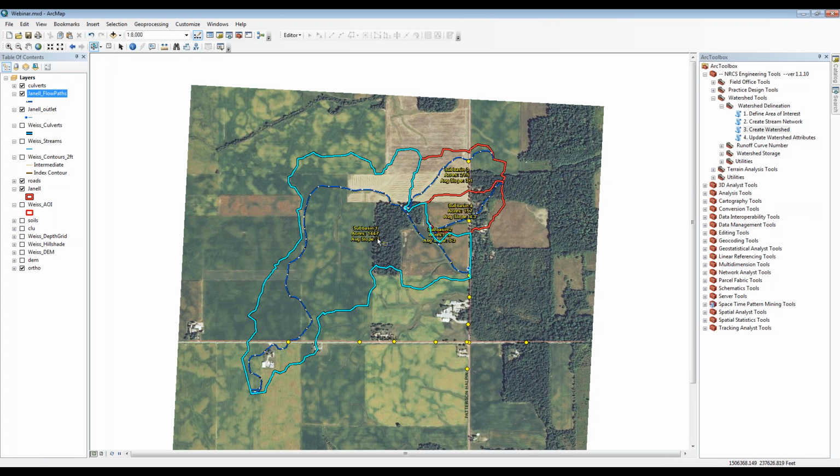and slope. One of the things that I'd recommend if you're going to do a large watershed and then do individual reaches or laterals, I would run the Create Watershed tools once for the entire watershed. Just do that main subbasin and then come back and run it a second time, assigning a separate name to the watershed, like subbasins, and do each of those branches separately.